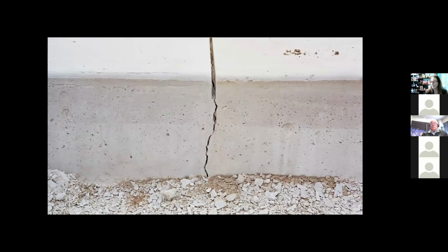So this is an excellent example in this image of a saw cut joint. Whether it's deep enough is up for debate. It might have been an early entry saw, but in this instance, it activated at the joint. That's what we want. That's how we design concrete. So one of my largest frustrations is cracks are normal, everything cracks. You can tell it where to crack, and you can design your jointing pattern to make some beautiful concrete.